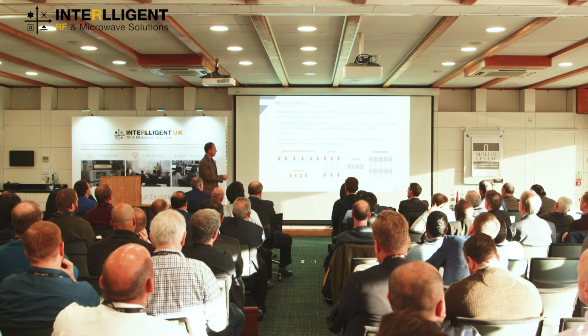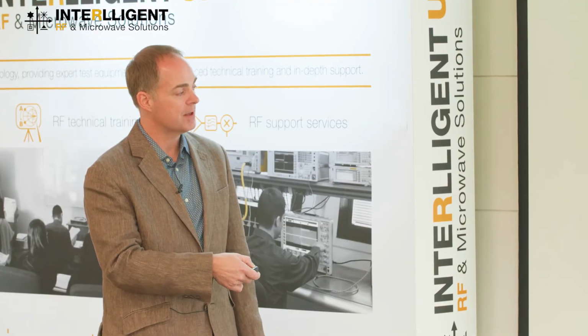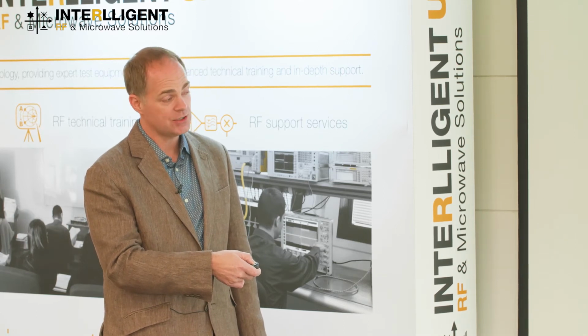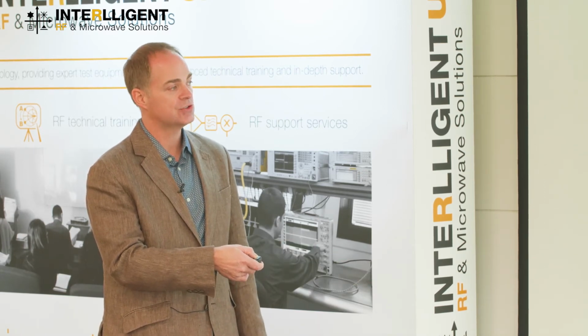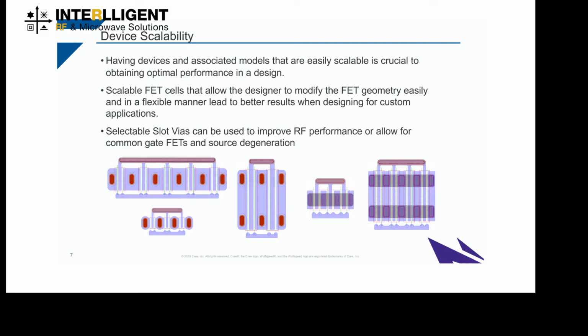You can also have different size gates that are scalable for lower frequency versus higher frequency applications. You can also, if you need source degeneration, or if you plan on using, say, a common gate configuration for a cascode device, use strapped sources instead of the slot vias. It does increase the source inductance, but in the case of a low noise amplifier, for instance, sometimes you actually want that, right? You want to use source degeneration to help stabilize the device and pull the noise circles in closer to the gain circles.